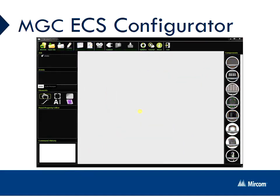If you are going to be connecting a QX Mini to a UL or ULC listed fire alarm panel via relays, or you're going to be connecting to a compatible Mircom fire alarm panel via the SLC loop, you'll have to utilize the panel inputs so that when an input is activated, an output zone is turned on, as well as a message or tone. Since there are 2 different methods of using the inputs, I will create a simple job for each.